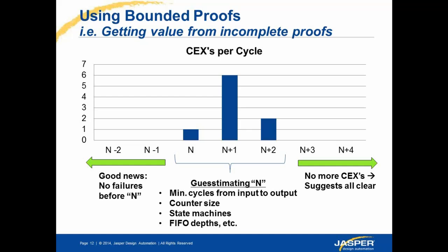And they say, let's say I have run this design till a depth of n or n plus 2. And if I haven't found a counterexample till that, it might run for a day, it might run for a day or 2, but then if the tool reaches this depth, it is good enough for me to sign off on my formal verification effort.